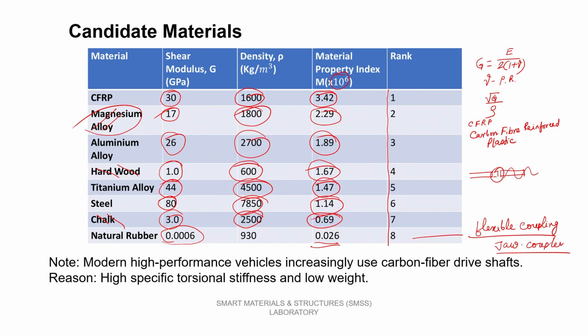So, we would then practically have CFRP as a possibility, aluminum alloy as a possibility, titanium as a possibility, steel as a possibility. Okay. So, these are the 4 practical possibilities with us, and out of that, even though steel is the lowest, you will see later on that steel can regain its position because of another possibility through the Ashby triangle.